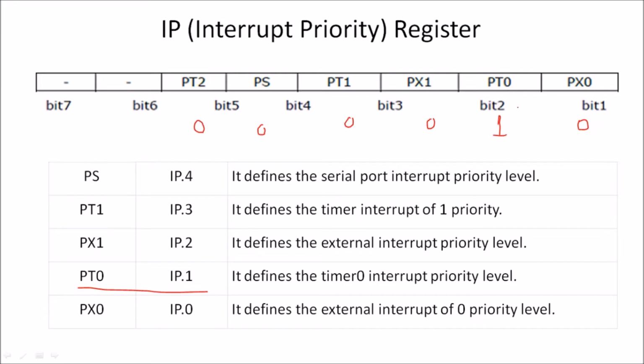priorities of interrupts. So the priority of one interrupt can be changed, and it is required when more than one interrupt occurs simultaneously. Only then will the microcontroller go as per their priorities. So even if a hardware interrupt and this software interrupt, that is the timer 0 interrupt, occur simultaneously, first the microcontroller will provide service to the timer 0 interrupt, and then it will go for the other interrupts as per the default priority.